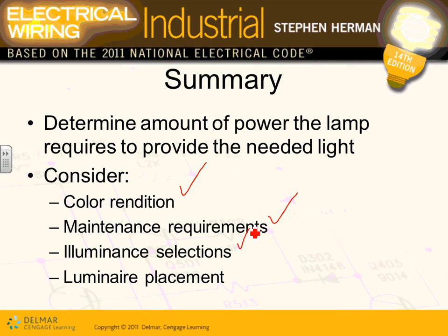Luminaire selection and foot candle is a big deal, and of course, luminaire replacement or maintenance is a big deal. All these will point right now to the LEDs. All these will be pointing towards using LEDs in this day and age. It used to say high intensity discharge, metal halide, high pressure sodium. For the most part, we're showing LEDs.